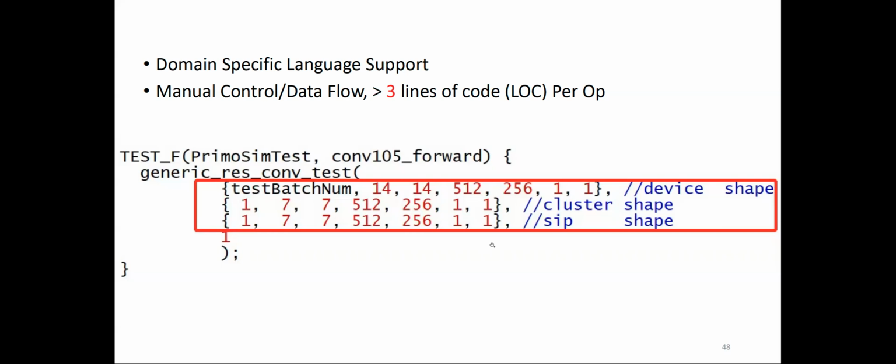And then the underlying compilation framework will take this kind of DSL description and generate the corresponding DMA or control flow, and the data flow, to hide these details of this data flow. So as a DSA part, we abstract all those compilation away. We just define the shape, and then the compilation framework will compile this data flow scheme based on this shape to the corresponding DMA operations.